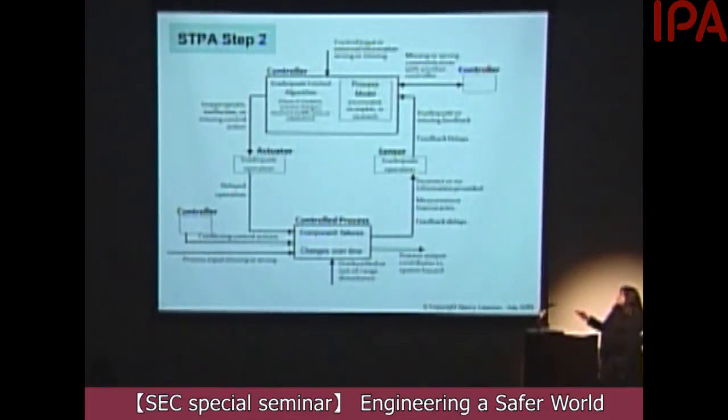So how do we solve that problem? Well, one thing is to provide feedback. So we provide some indication that the valve has actually opened. That might be a way of preventing that problem. So what we do is perhaps put in a flow monitor in the system to show that water is actually flowing through the system. There may be other solutions, other design techniques. All we're doing here is trying to help the analyst and the designer, the software and the system engineer, create a safe design.